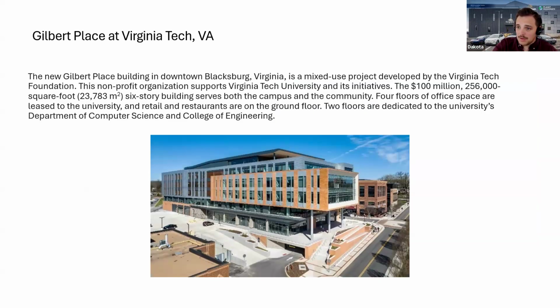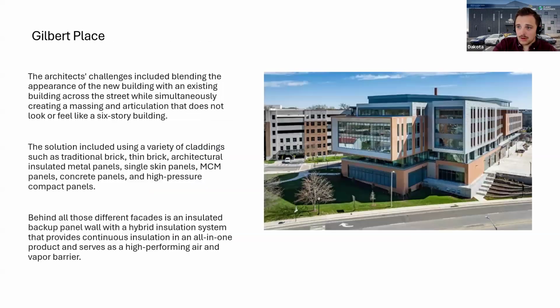Nobody wanted it around, but because we were able to introduce the IMPs, creating that nice, consistent rain barrier behind there, we were able to mass out different parts of the building so that it looks like little chunks. And this does a good job of communicating the intent of what's happening inside the building, but also breaks up the visual mass of how truly large this building is while still keeping the energy performance in front of mind. So we have some brick down here, some extruded plank, some wood finished metal panel, whatever it is, and some exposed IMPs at top.